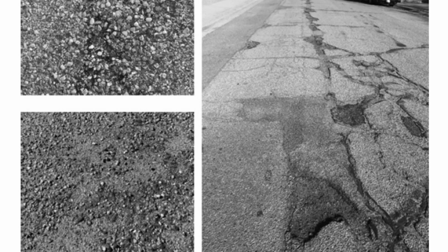Adequate compaction is required to allow bonding between aggregate and binder. Studded tires may break the bond between aggregate and binder. Small raveling may be fixed by patching, microsurfacing, or chip seal. Large raveled areas require an overlay or surface replacement.